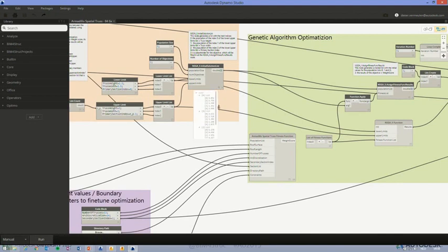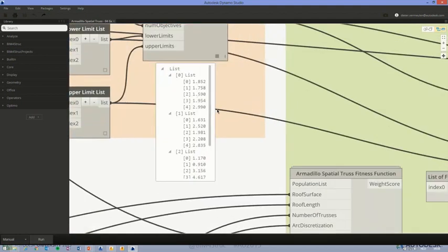which is, well, I forgot to tell you that. If you have that arc, in Robot, it didn't generate an arc, it generated lines. It's discretization. So in analysis software, you don't get that curved object. It's a chained line, in fact, representing that curved object. So that's a discretization parameter that has been used in here for that.